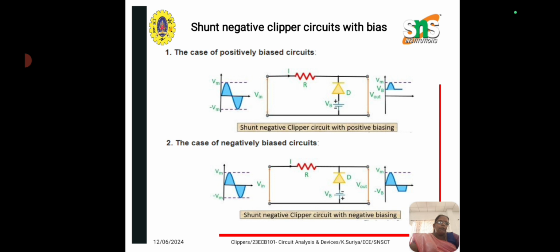During the negative half of the input cycle, the diode gets forward biased due to the supply voltage but is reverse biased by the battery potential. Thus the output signal is achieved until the supply voltage exceeds the battery potential. As the supply voltage exceeds the battery potential, the diode completely starts conduction and the signal does not appear at the output.